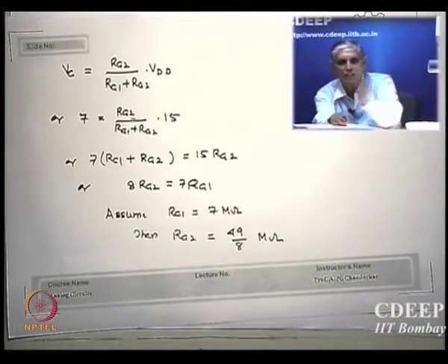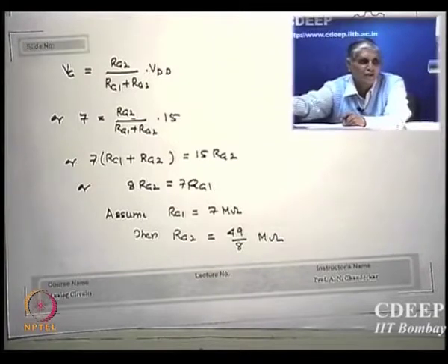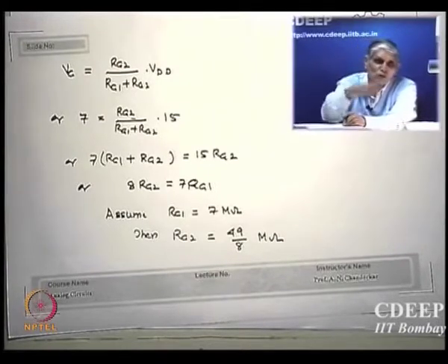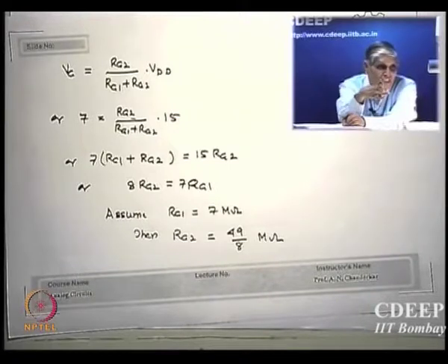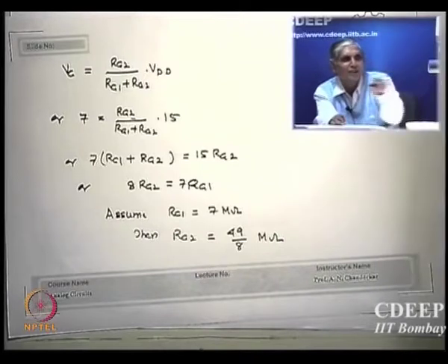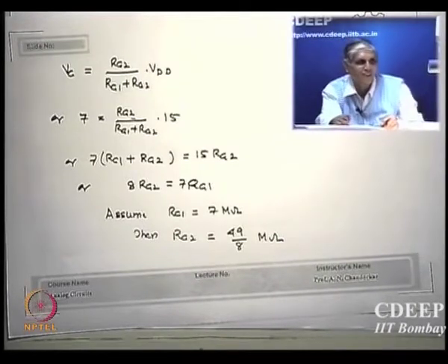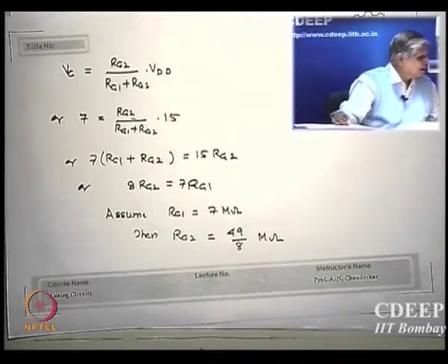Why do we do it this way? Because someone will tell me, I want a gain of 100, or 50. Then I will have to do a reverse calculation and see how much gm I must provide, and how much power I will dissipate, so I should not go beyond this wattage. So I will fix some values and start calculating back till I get numbers where I can say, okay, it will meet all your specs. This is what design is about. So I did this.